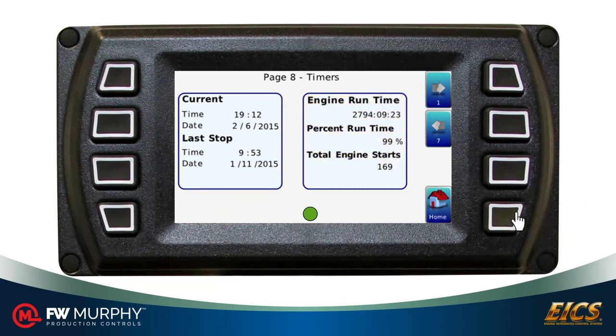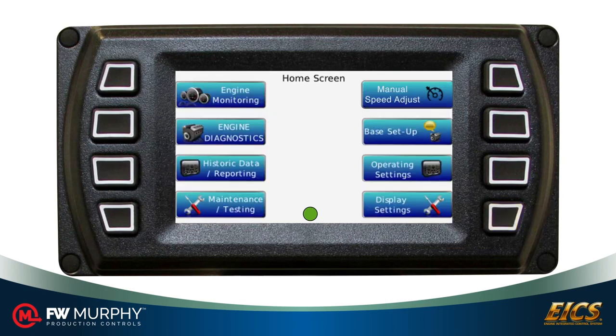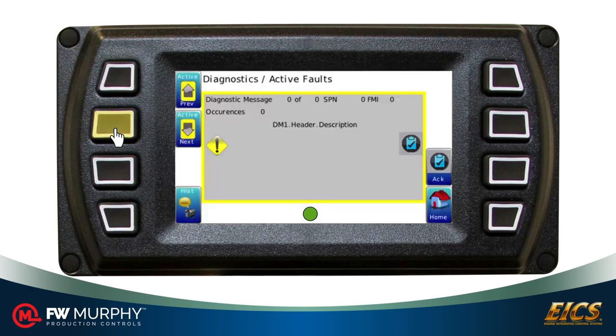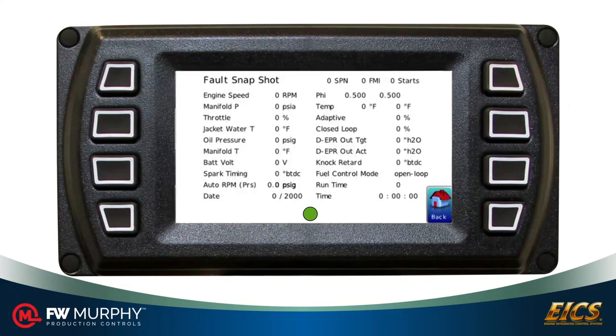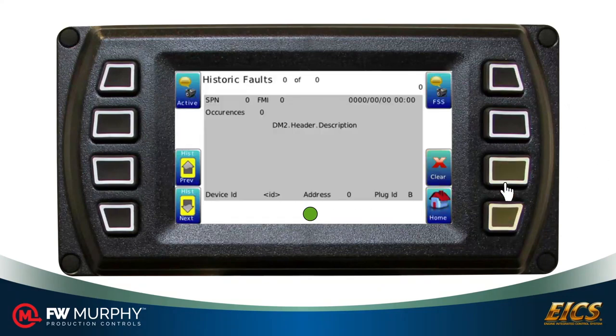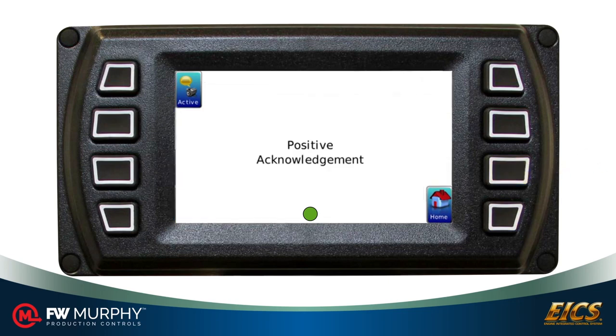To navigate any setups, press the Home button. On the home screen, you can view Diagnostics. This shows the faults and shutdowns. Clicking on the Historic button takes you to the Historic Alarm screen. On the Historic Alarm screen, clicking on the FSS will show the fault snapshot for that alarm, and clicking on the Clipboard Clear button will clear all the historic alarms.